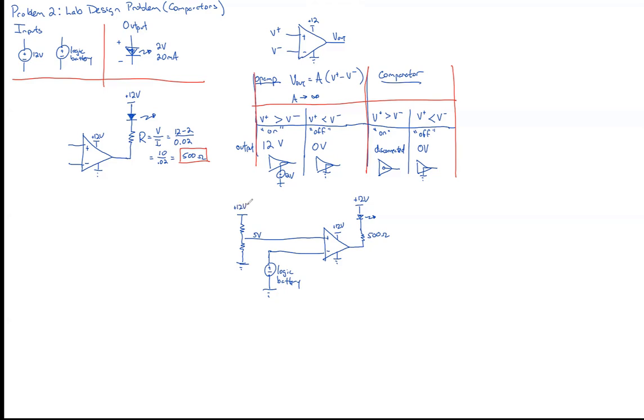There are different ways we can make this voltage divider. In the problem, you can use any kind of resistors you want, but I'm going to add a restriction up here. All the resistors in any kind of reasonable design are going to be between 1 kilo ohm and 1 mega ohm. If the resistors are too small, let's just take it as a reductio ad absurdum argument. They're equal to a fraction of an ohm each.